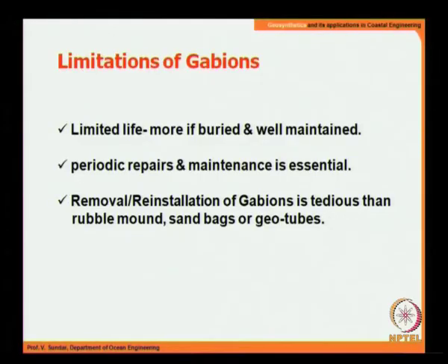Limitations: limited life, more if buried and well maintained. Periodic repairs and maintenance is absolutely essential. That applies not only for gabions, but all other geosynthetic products. Removal and reinstallation of gabions is quite tedious compared to just a rubble mound, because in a rubble mound you are going to have bigger stones, but here it is going to be a big problem.